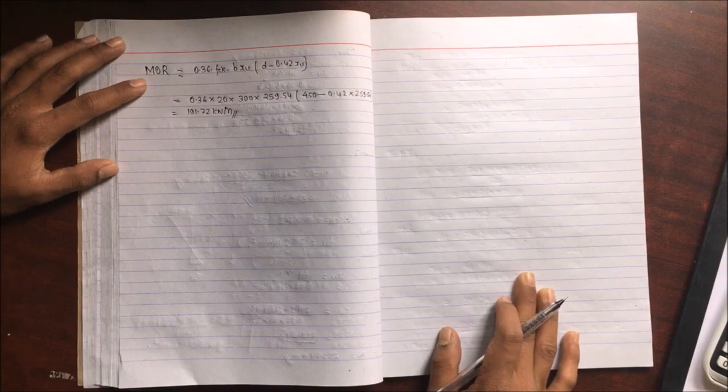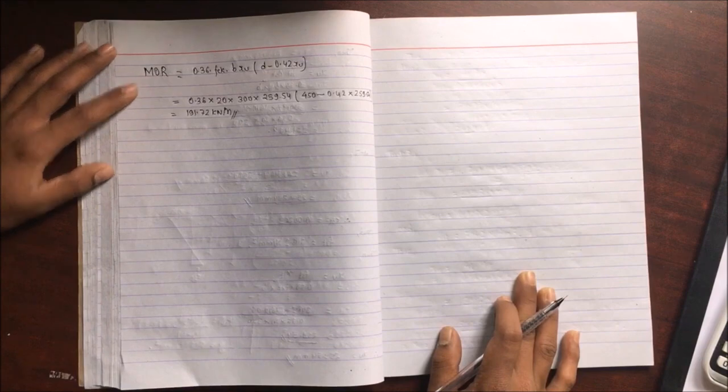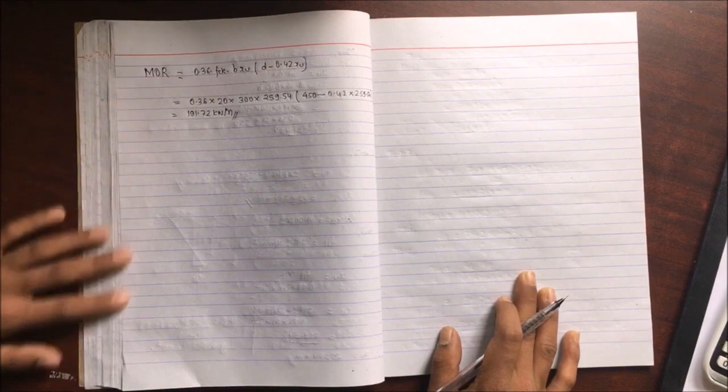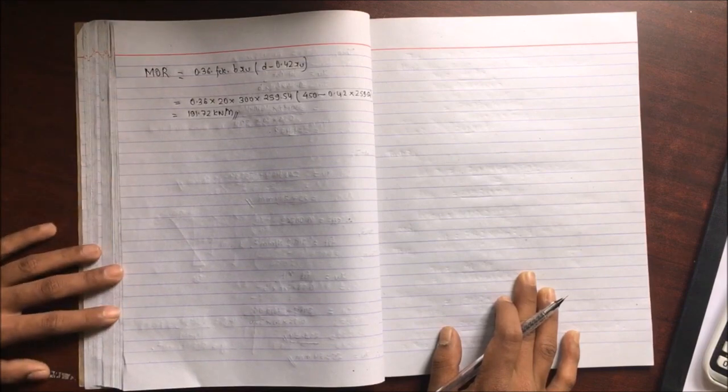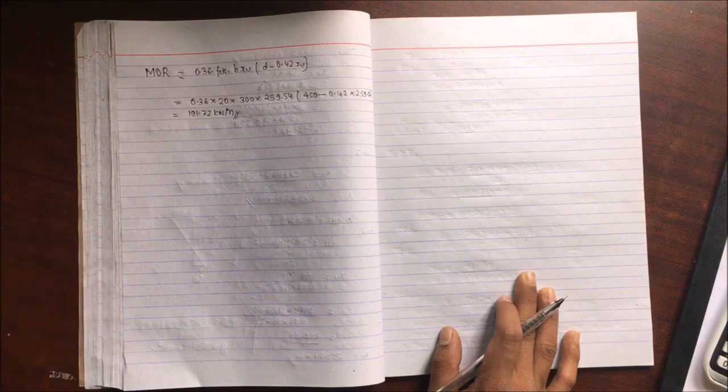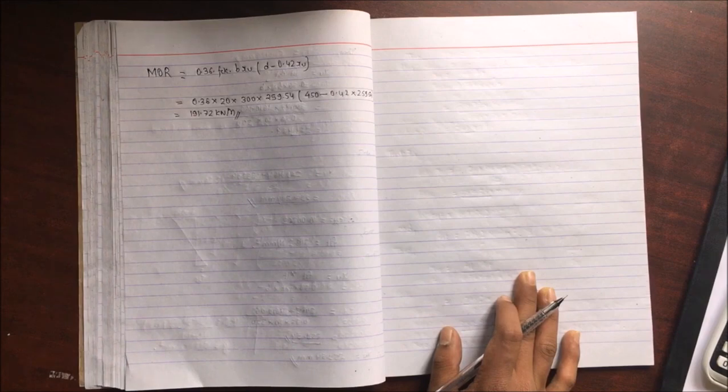So this is the difference between a singly reinforced beam section with over reinforced case and under reinforced case. In case of under reinforced, the MOR can be calculated by using the value of actual depth of neutral axis, but in case of over reinforced beam section, the value of XU is calculated by using strain compatibility, as the actual depth is much greater than the limiting depth. So this is the difference between these two sections, that is over reinforced and under reinforced.